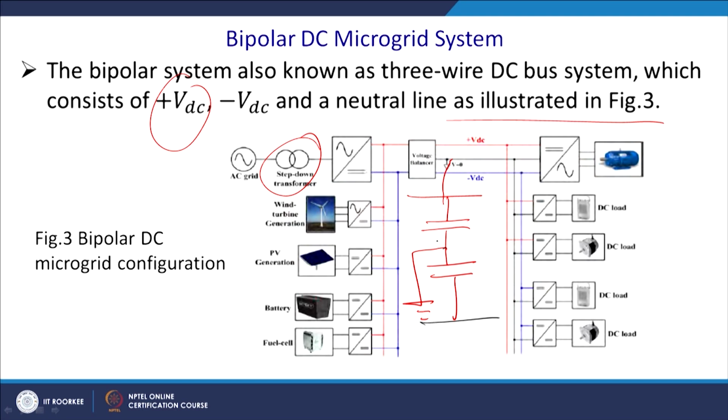The other lines are the same, but in this configuration you do not require the zero potential. Here it is a wind turbine, here maybe it is a battery, but you may have a DC load and you can configure accordingly. You have an adjustable speed drive, with AC DC DC. So, generally you will give plus minus and that will be converted into AC.